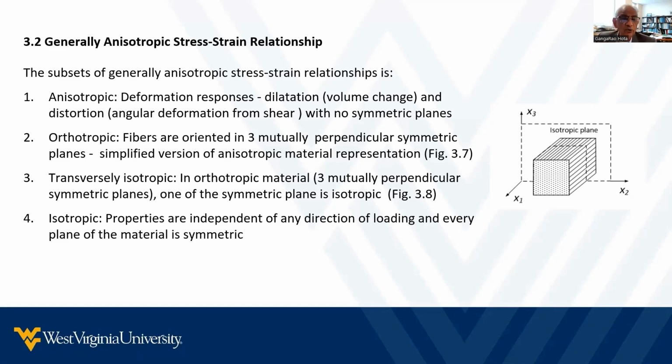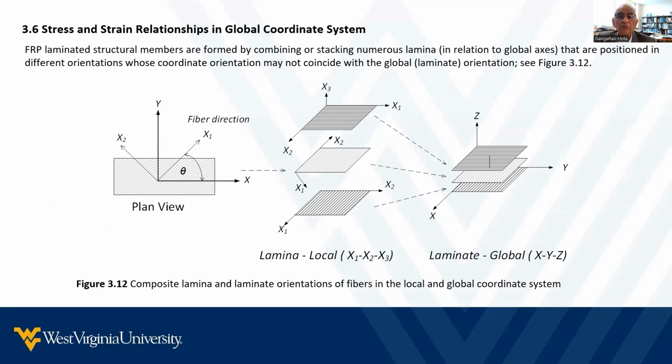So what I'm trying to do here, in terms of this plane stress problem, is convert the orientation of the fibers in their local axis, meaning lamina-based axis. You see the lamina in this? I have fibers running in x1 direction. I have fibers running in 45-degree directions. I have fibers running in x2 direction. All kinds of things are happening.